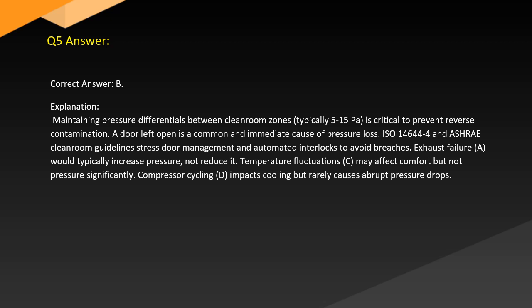An exhaust failure, A, would typically increase pressure, not reduce it. Temperature fluctuations, C, may affect comfort but not pressure significantly. Compressor cycling, D, impacts cooling but rarely causes abrupt pressure drops.